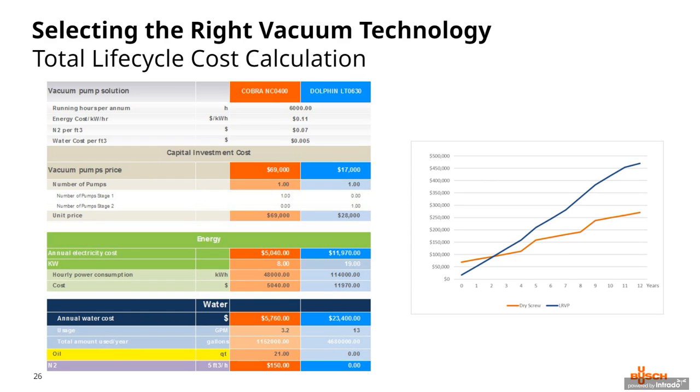Here we're comparing the total life cycle cost of ownership, and we do this using the calculated capacity requirements from the last example, and we size it for both of the systems. These are the prices for the basic accessories seen on the previous P&IDs, and we omitted the electrical control. You can see that the initial investment for the dry screw is higher, but it requires less power. The energy shown is the actual calculated absorbed kilowatt power, and you can see the additional cost that adds up over time. The dry screw pump does utilize cooling water, but the once-through utilizes more.